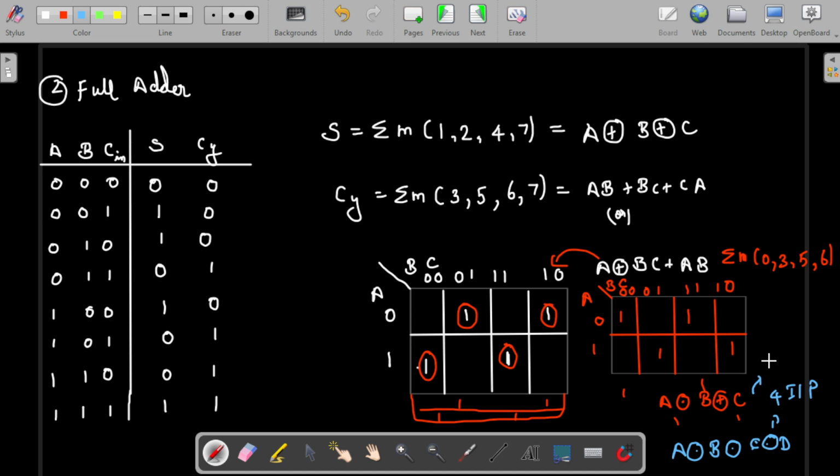So this is for 3 input. I hope you are able to understand it, right? If it comes in 4 inputs and is repeated like this, then this is 4-input XNOR. Here it is 4-input XNOR, both the same. For 3 and 4 inputs it is the same for XOR, so there is no problem. But in the 3-input case, one will have one XOR and another XNOR, whereas in 4 inputs we have everything as XNOR.